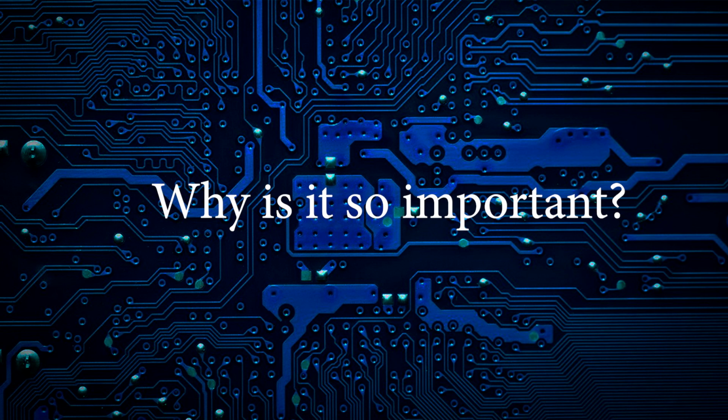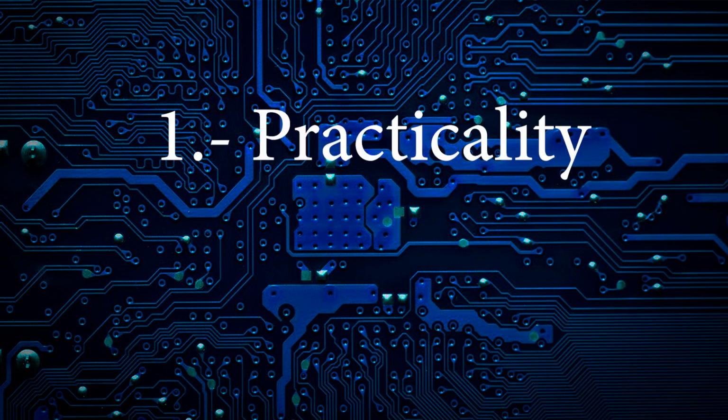As we mentioned before, it's a matter of practicality and efficiency. In terms of practicality, more specifically in digital electronics, generating a PWM signal is very easy for any microcontroller, because we only need a timing parameter. So it's the closest thing to analog control with only digital resources.